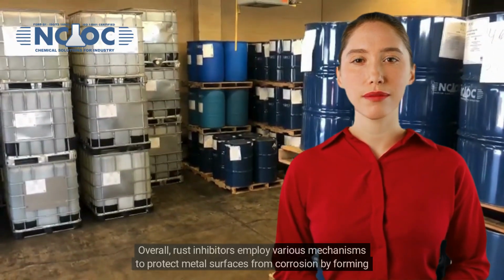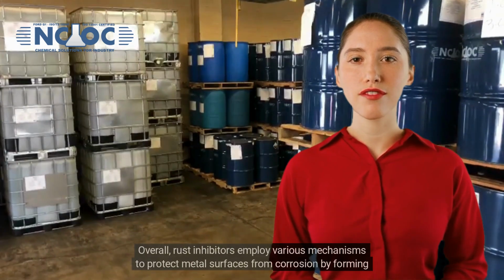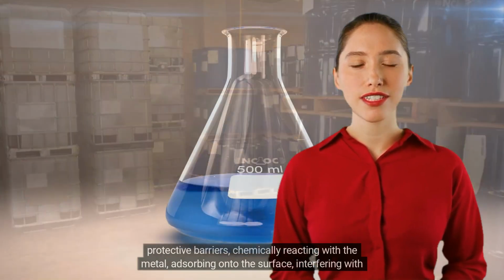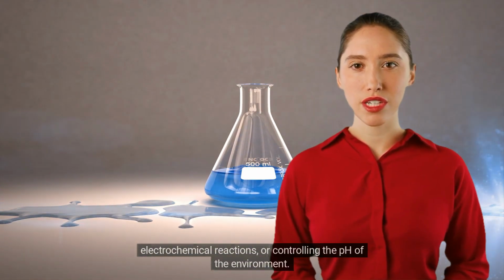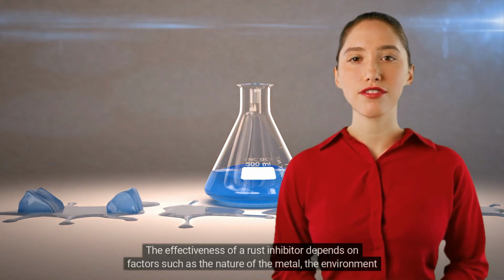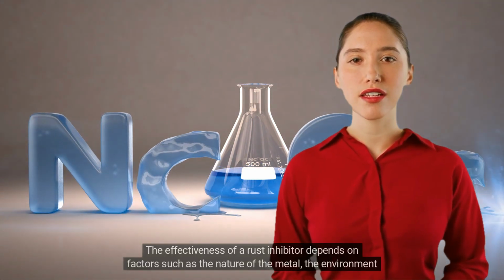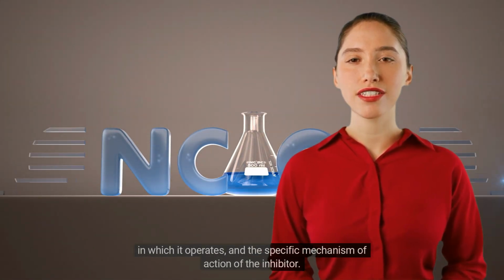Overall, rust inhibitors employ various mechanisms to protect metal surfaces from corrosion by forming protective barriers, chemically reacting with the metal, adsorbing onto the surface, interfering with electrochemical reactions, or controlling the pH of the environment. The effectiveness of a rust inhibitor depends on factors such as the nature of the metal, the environment in which it operates, and the specific mechanism of action of the inhibitor.